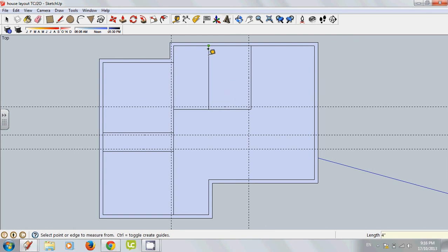Now this dividing line between the bathroom and the utility room, I'm going to make a little bit thicker and make it 6 inches to allow for a plumbing stack to go through. Because you've got a bathroom and utility room. A plumbing stack is a larger pipe that goes right up through into the attic and allows ventilation to the drain and waste system of your house.